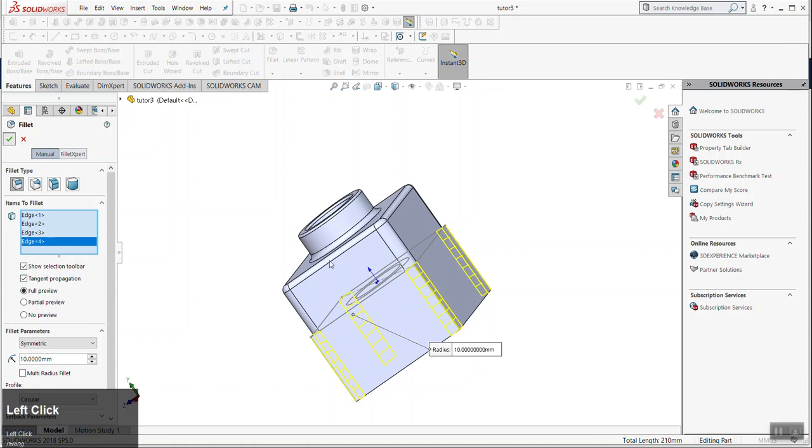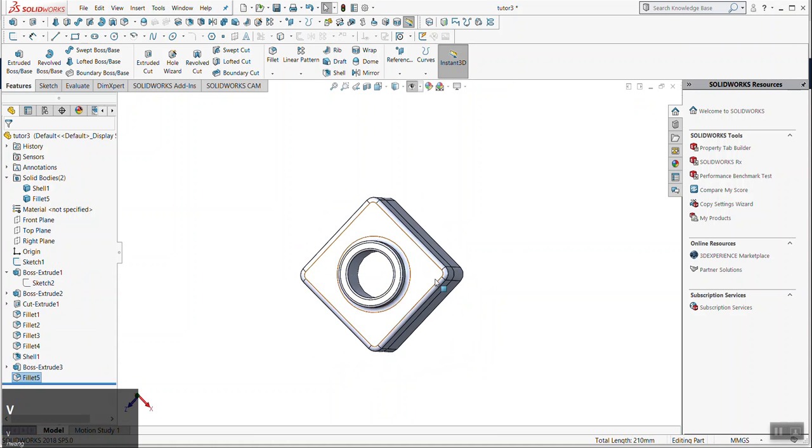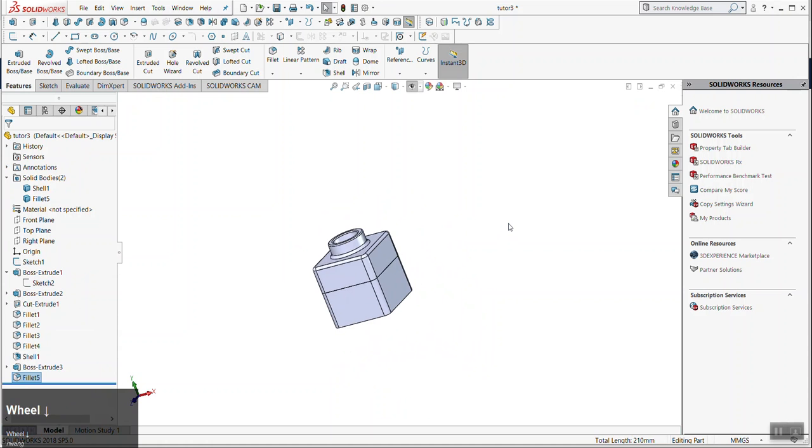Again, in my opinion, and what's pertinent to industrial designers, is 100% the linking and external referencing thing. That becomes a rat's nest when you're working with other people. And the reason why I'm specifying for industrial designers is more often than not, when you're working in CAD, you're still in a bit of an exploratory phase. You're not doing anything final. You're translating a sketch. You're figuring out some form in a little more detail. And to begin with, it's a better workflow to be within one part so you don't create external references.